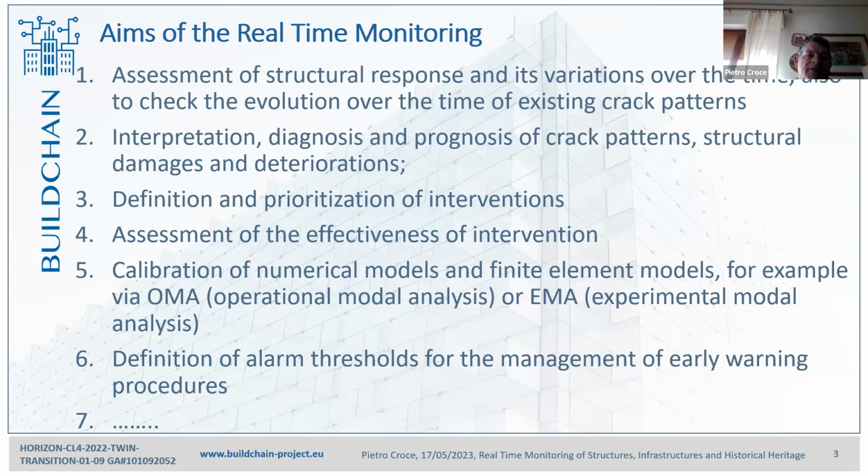Also, in view of the definition and prioritization of the interventions, assessment of information by comparing the structural response before and after some kind of intervention, the calibration of numerical models and finite element models through operational and experimental modal analysis, definition of alarm thresholds for management of early warning procedures, and so on.